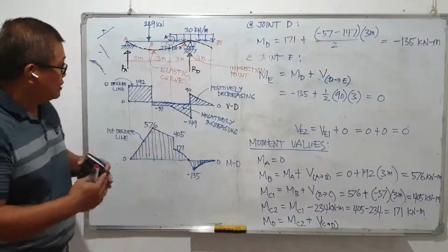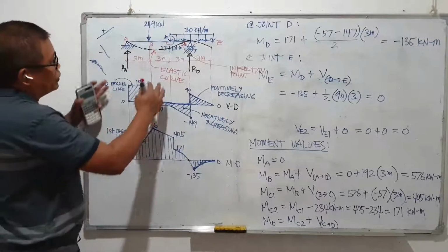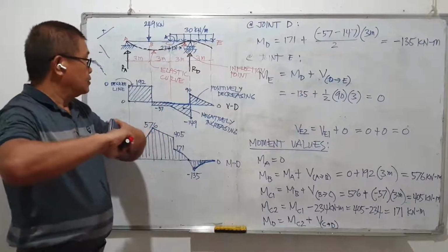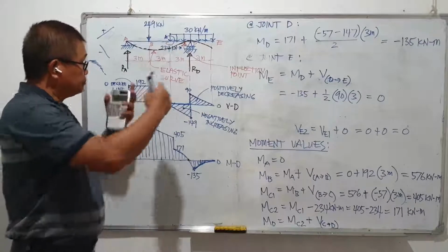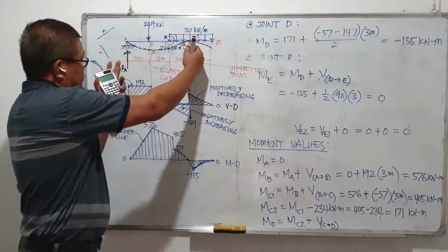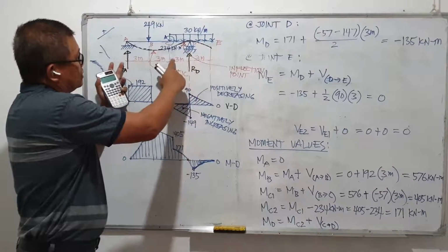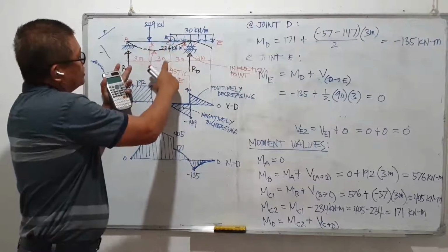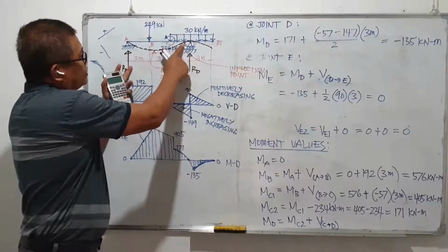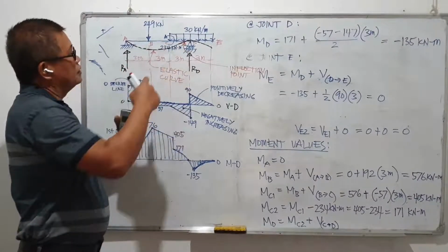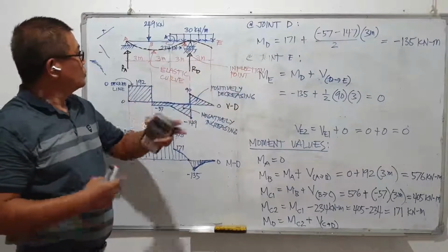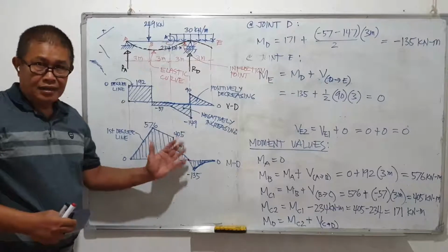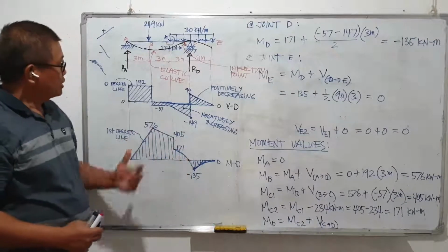So if it's not sufficient for the whole span, then we have to splice for the distance that is required. In this case, like this 9 meters, and if we have only 6 meters, then our splice should be located more or less at the location of the inflection point, or close to that point where the moment is not quite large. There, we can still make a splice.